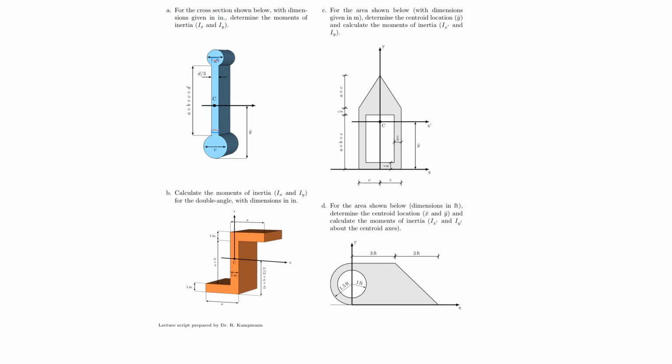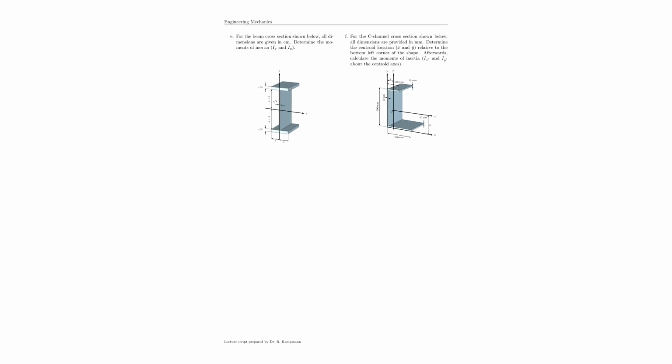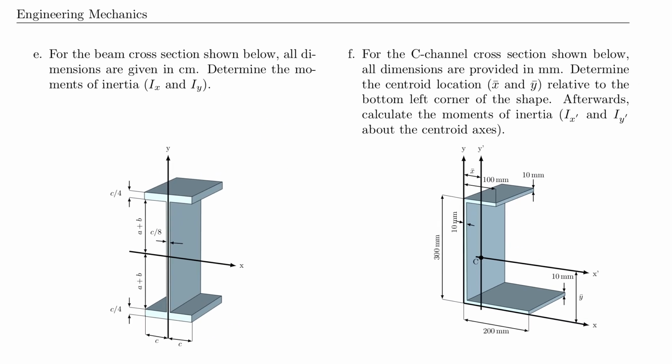So I think that deciphers the problems on this page. Let me move on to the last page. Here you see very common structures. Here an I-beam, this should be pretty much a walk in the park after what we talked about in this class or in these video lectures. Simple shapes, and you know that it's doubly symmetric, so you know exactly where the centroid location is. Notice here that the centroid location is actually outside of the C channel, and that is sometimes confusing to students, but you can still calculate it as you usually do.